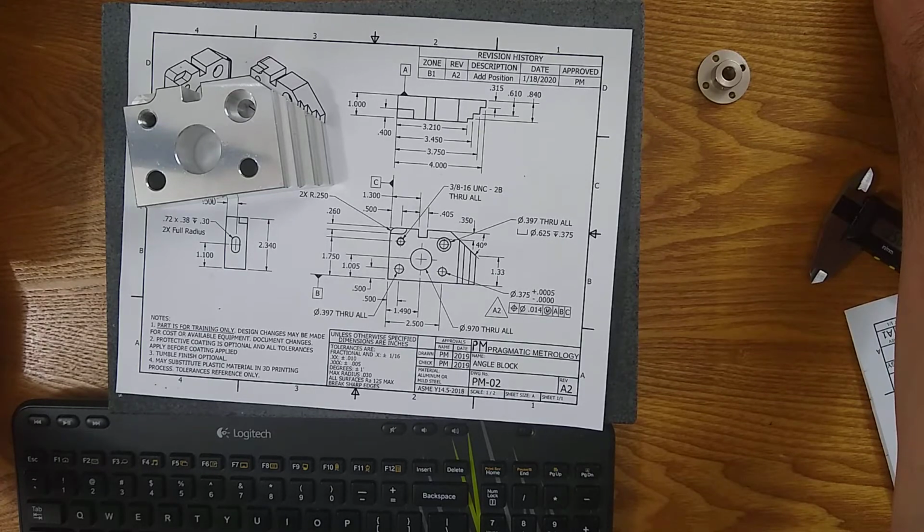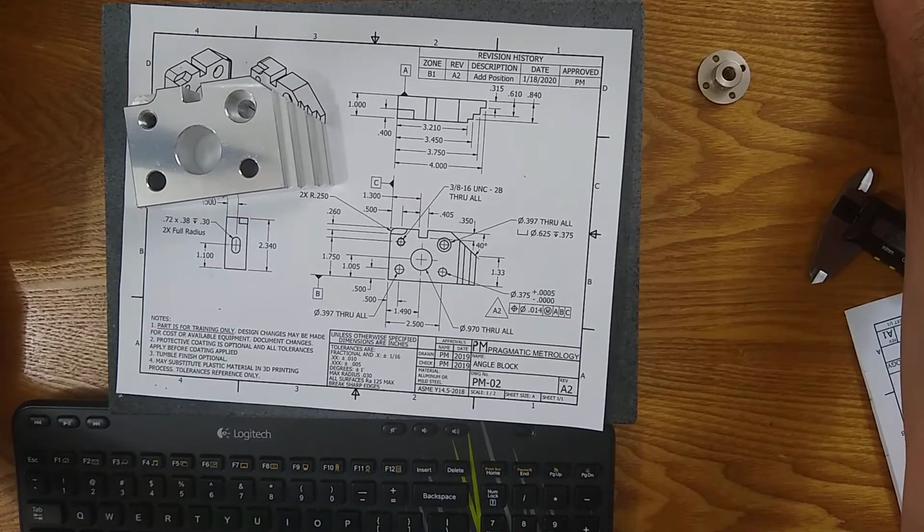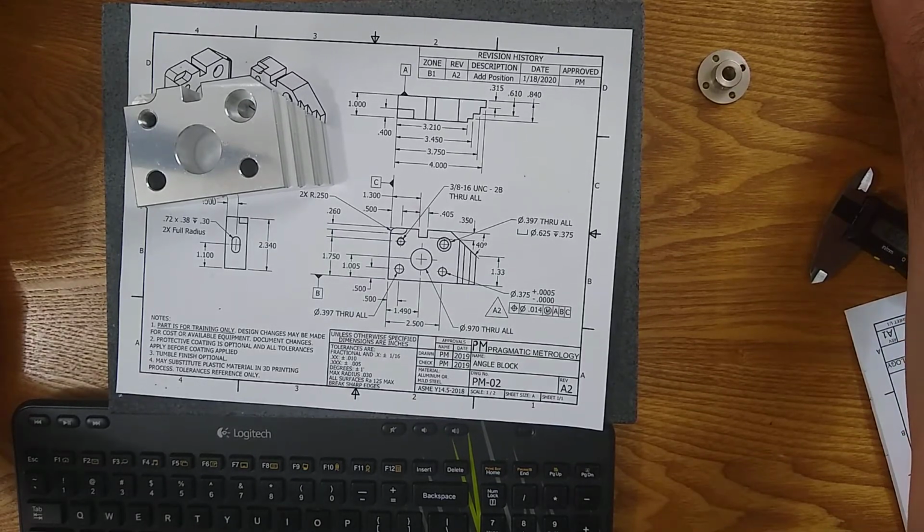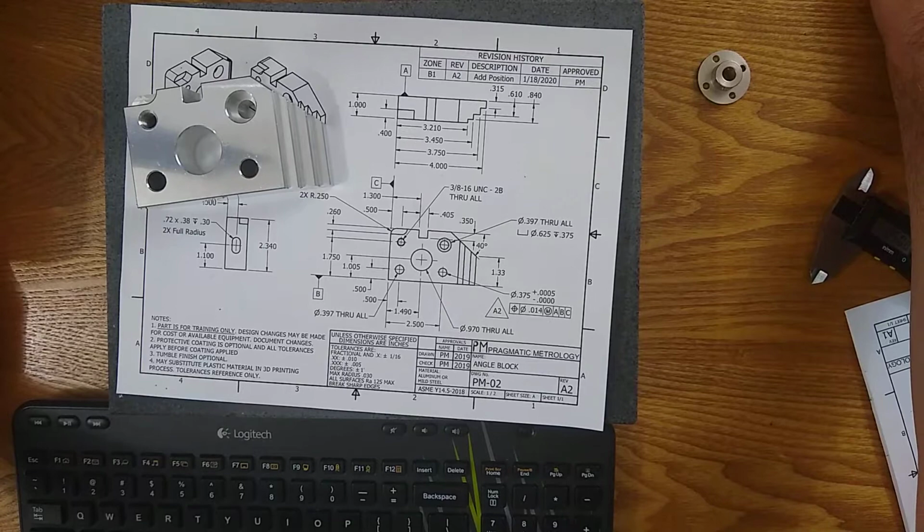Hopefully you wouldn't use a caliper on this precision tolerance, but you could have grabbed here and here and gotten 970 with your caliper. Now, you also could have used the CMM, or a gauge pin. Only the 966 would have gone through with a gauge pin, so that would have been obvious. If you use a CMM, it's going to tell you the low, high, and the average, but if you only look at the average, it's going to pass.